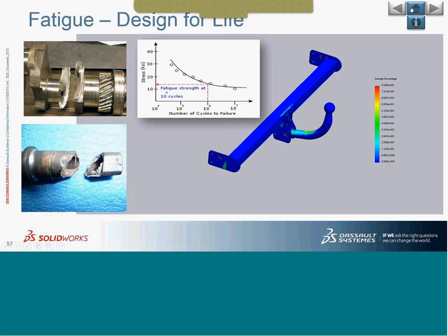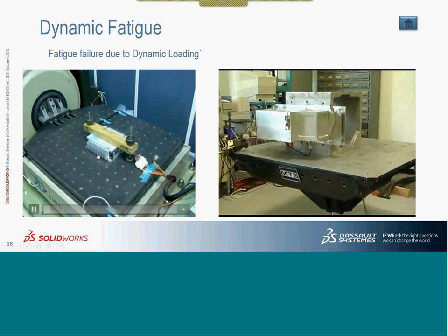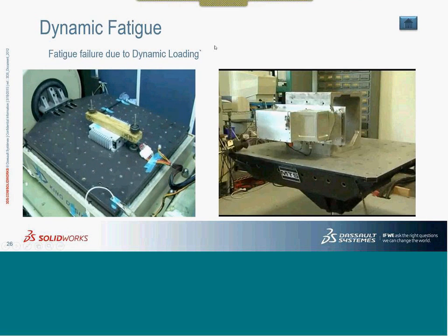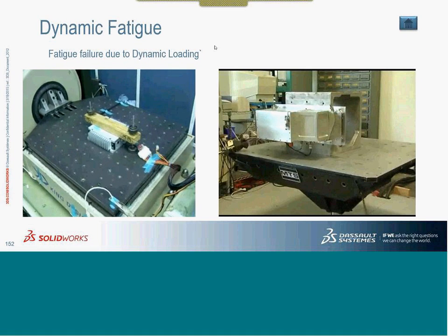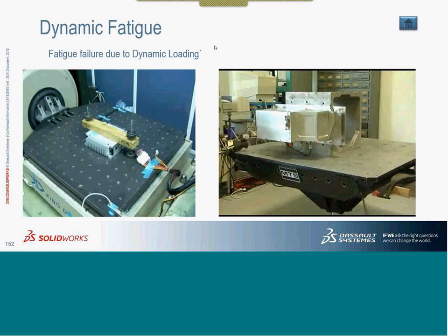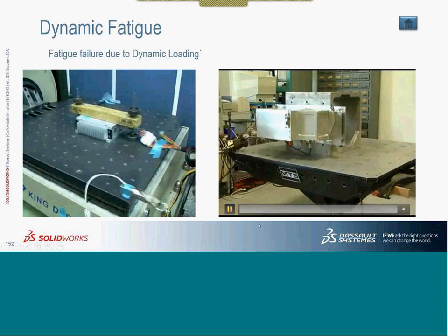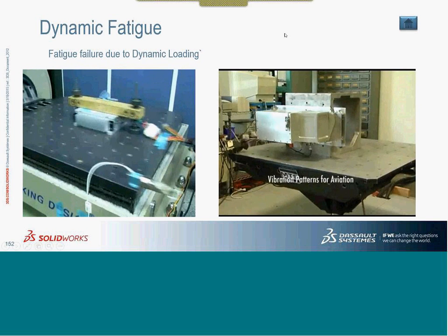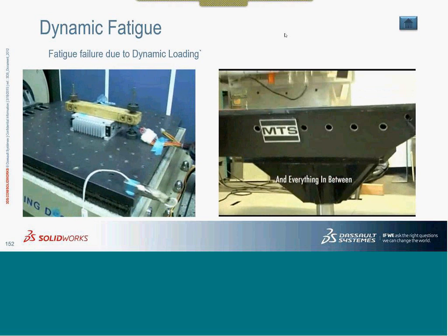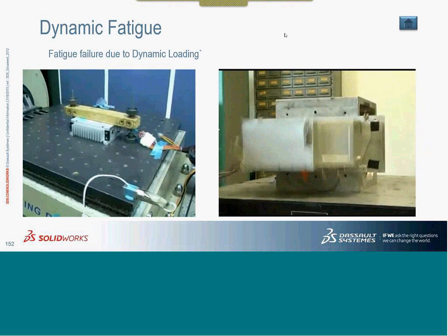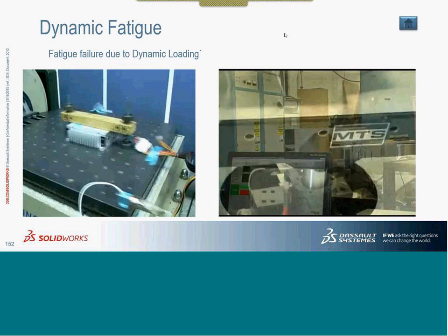Other than that, we introduced in 2015 that we can also simulate dynamic fatigue. What we are discussing as of now, or what the software had, was more static fatigue, where the loading comes in a slow and steady manner. Whereas it could also be vibrations coming randomly, and you want to understand the life of the component. With random loads, the logic is not that straightforward, and it involves more involved topics.